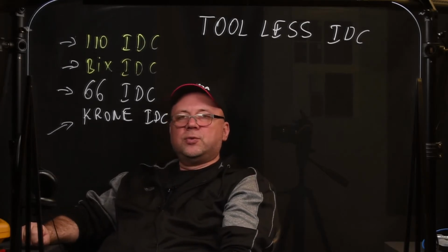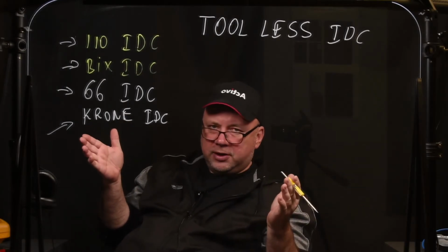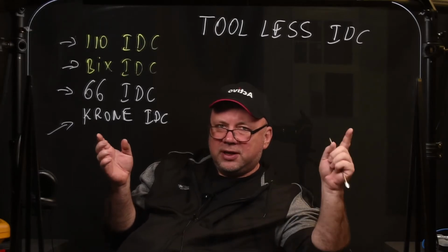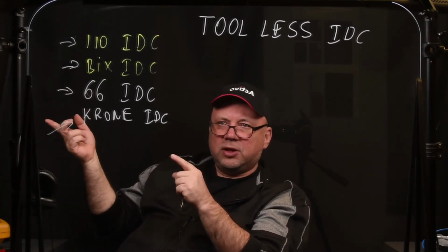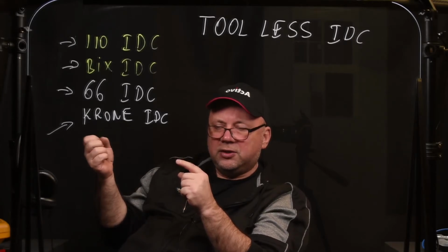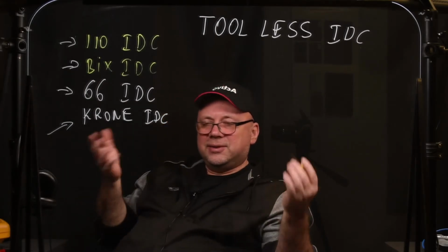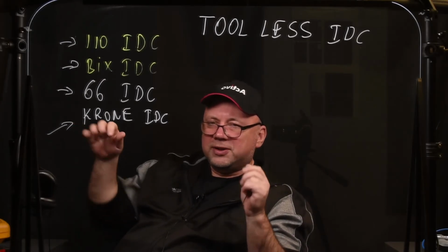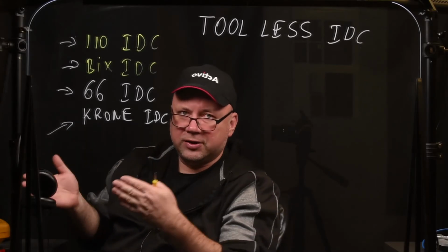Excuse me, 328 feet is the limit of end-to-end, but you never do 328 feet exactly, because remember, once you have end-to-end 328 feet, once you add the patch cords, then you're going to have the cable longer and the signal is going to get lost. If it's longer than 328 feet, you are going to have an unreliable connection. Okay, so 300 feet is the rule that we go by. If it's within 300 feet, yes, it's good, but the tester is going to test 328 feet, and if it's longer, it's going to fail you on the length test.